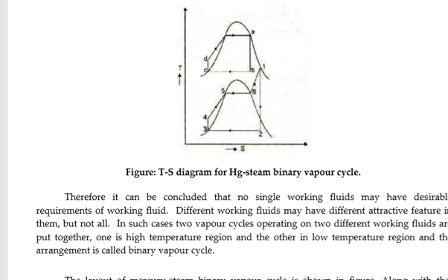And this is what happens. And then in this case, what happens? The saturated vapor goes from 5 to 6. The saturated vapor is heated by the external source, the furnace, in the superheater, 6 to 1. The superheated steam expands in the turbine and is then condensed.